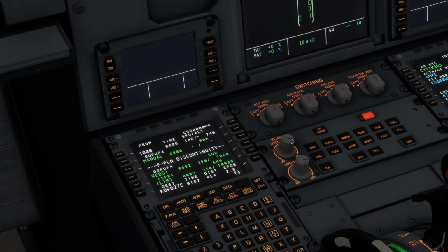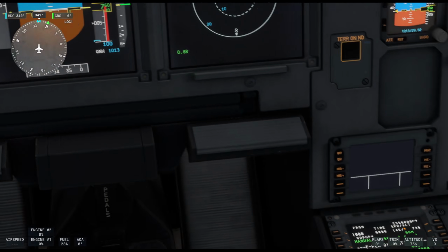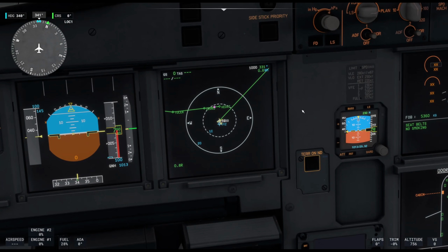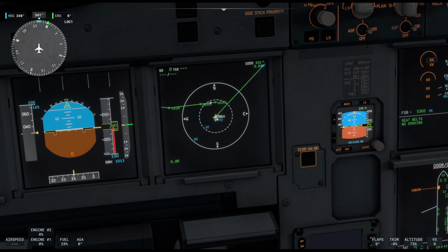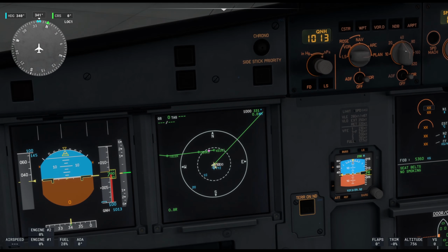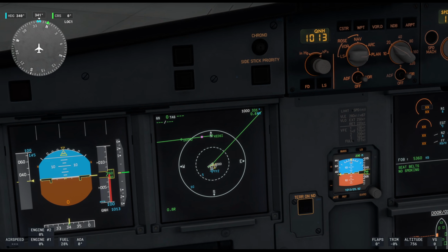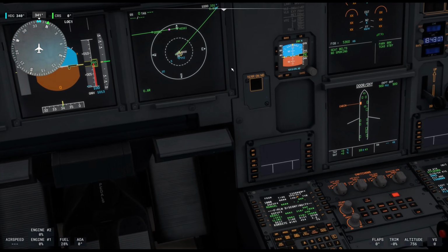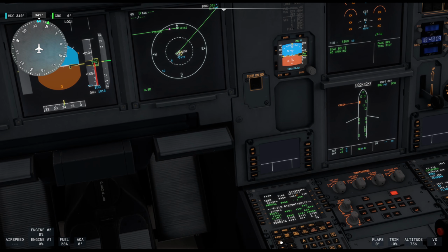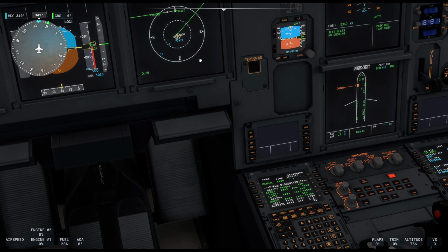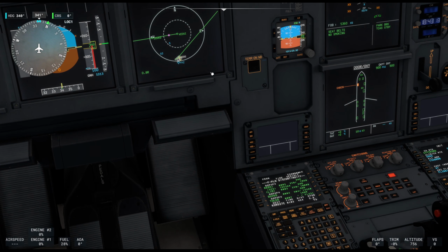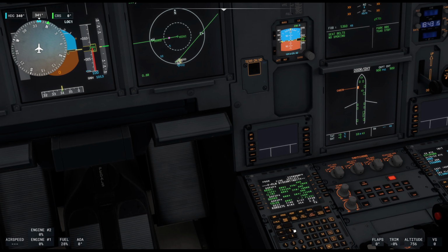So let's just press tab and close our EFB for now. And we're going to go through the rest of the flight plan to make sure there aren't discontinuities that we don't want. So I'm going to bring it down to, let's say 20 actually. Remember, zoom out so you can see both. Now let's start pressing the up arrow, moving on to the next waypoint and watching what happens here. So now we're on Kedsi. Keep pressing. We're just going to make sure that it doesn't say discontinuity here and that we physically don't see a disconnection on the map. I'll keep clicking through.